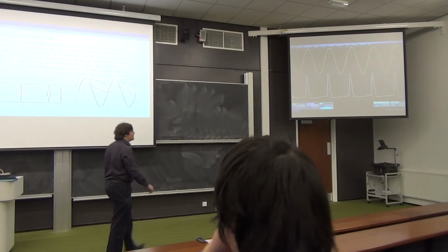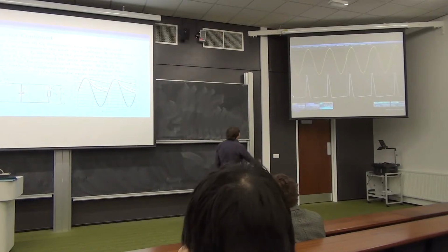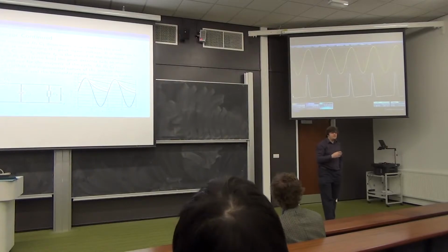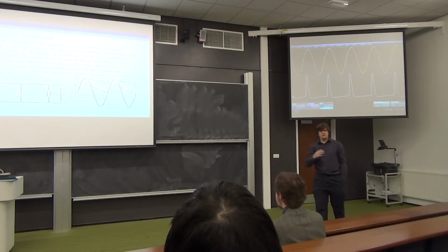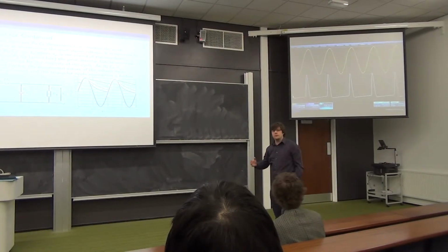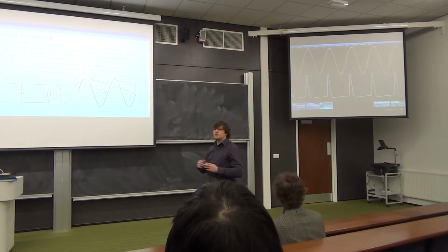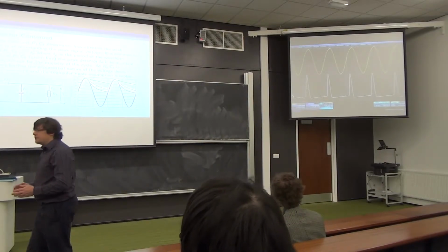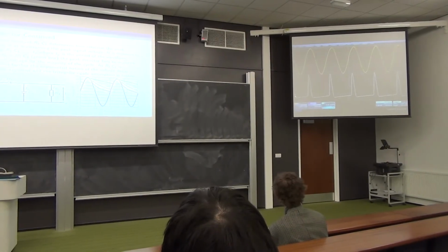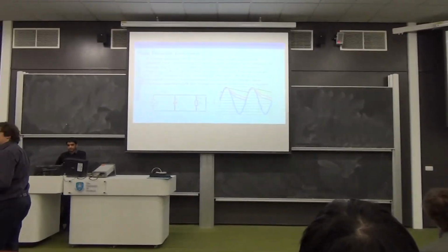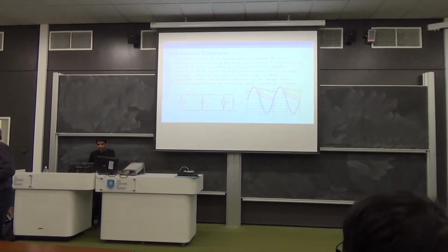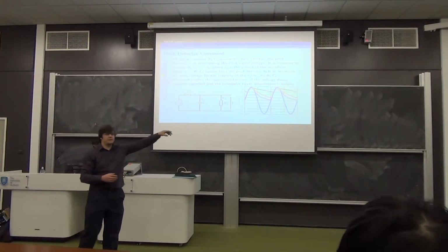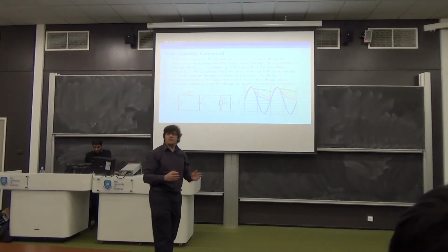Yes. Difficult times. So, if we reduce the time constant, the diode's going to have to conduct for longer, probably, to charge up sufficiently, because more charge will be removed per cycle. The diode will conduct for longer to recharge the capacitor because it's lost more charge. And this means that the current waveform is going to reduce in height, so amplitude, but be spread out in time. And overall, the area in the cyan triangle shape should get a bit bigger.